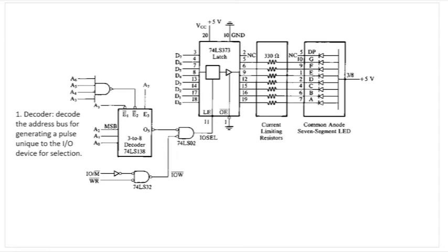Say, for example, we interface this device to address 58. Then using the AND gate, we can combine the address specific pulse with the control specific pulse.